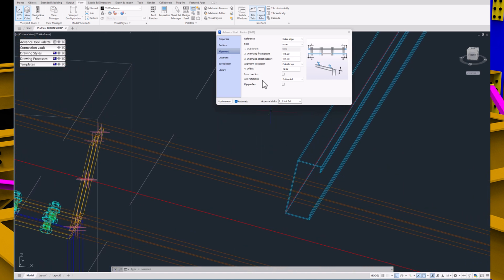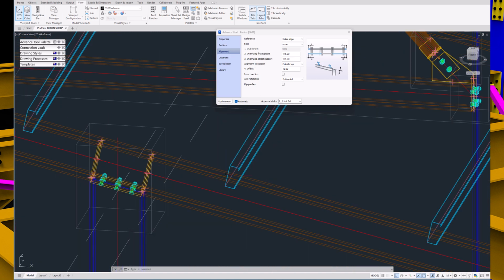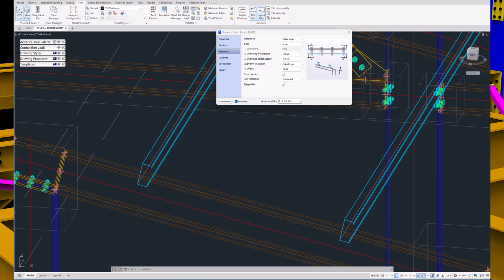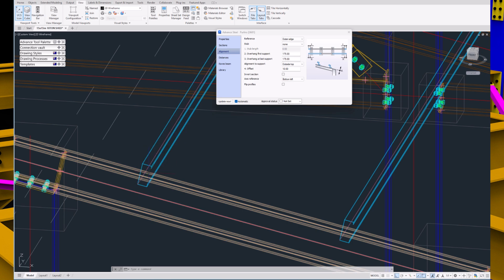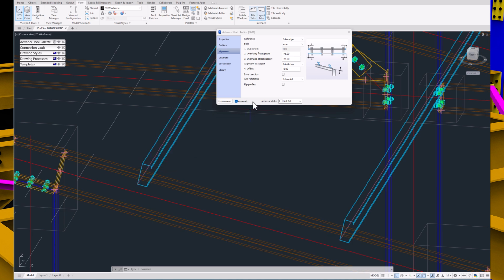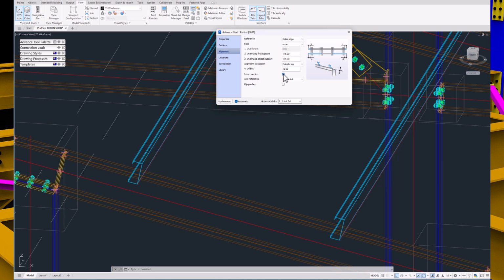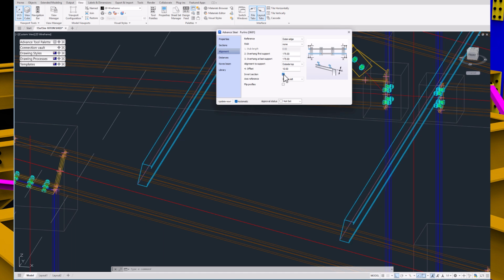Now, in order to change the orientation or the direction of the profile, there are two options, but you need to be careful because one option affects the position of the axis reference line, the one in red. For example, if you say invert, it just changes the direction of the profile. Let me deselect that and say flip profile.